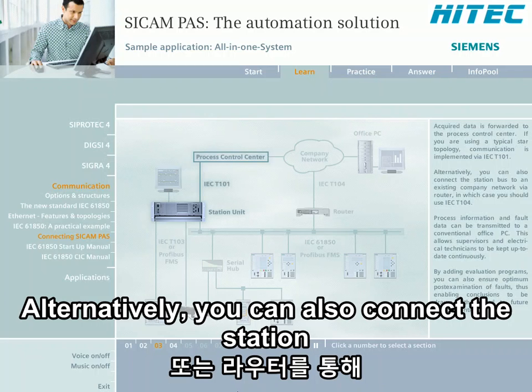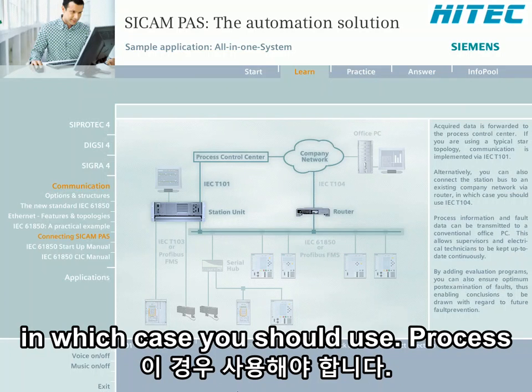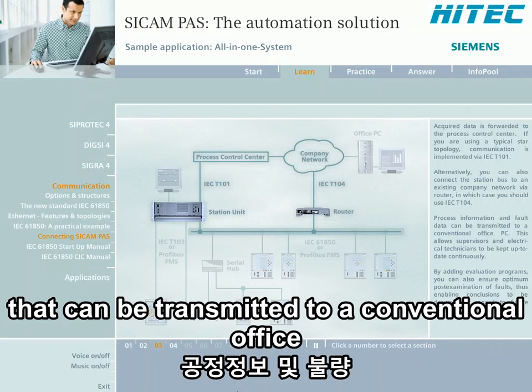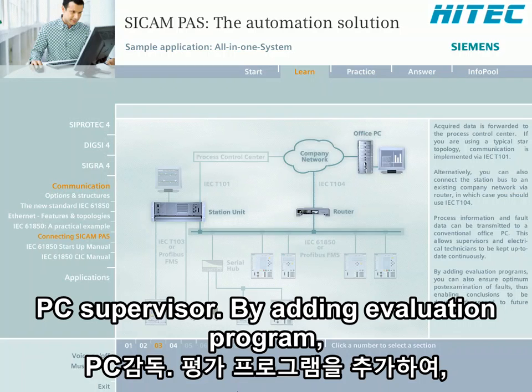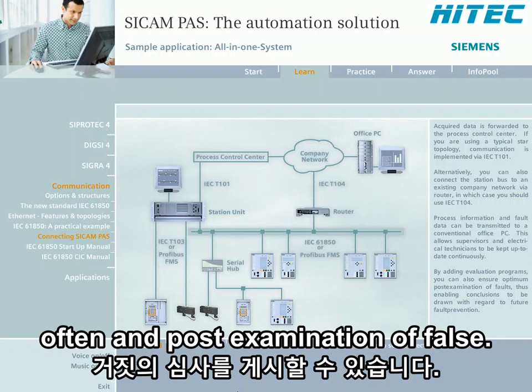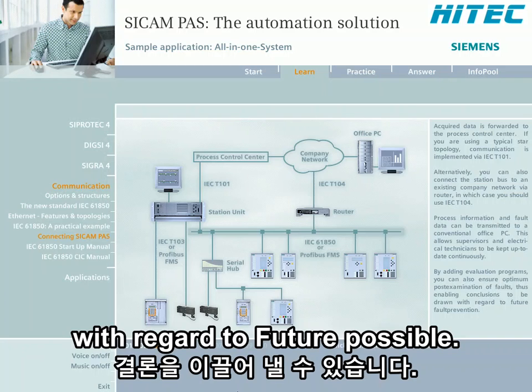Alternatively, you can also connect the station bus to an existing company network via router, in which case you should use IEC T104. Process information and fault data can be transmitted to a conventional office PC. This allows supervisors and electrical technicians to be kept up to date continuously. By adding evaluation programs, you can also ensure optimum post-examination of faults, thus enabling conclusions to be drawn with regard to future fault prevention.